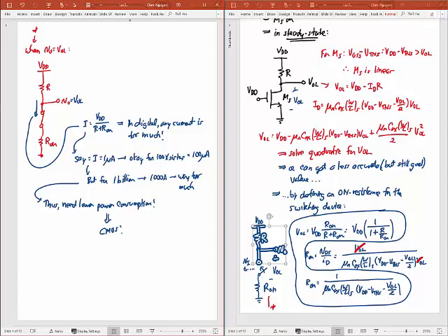So the solution to all of this, and what they did before they had CMOS, which is a complementary device, they put a transistor in place of that resistor and they made it work like a resistor. And we talked about resistors derived from transistors in your lab number 3, I think it was. You did something like that.